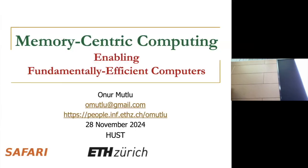Now, with two-dimensional technologies, if you have a planar memory, clearly there's not a lot of room to play with. But once you go to three-dimensional technologies, you can add logic underneath memory layers, and your cost is kind of hidden, right? Now you're not really reducing capacity. Yes, you can always say one layer can be more memory, so you're always losing capacity from that perspective. But you cannot get something without paying some cost. Does that make sense? The question is how much cost you can tolerate and what kind of system level benefits you get.